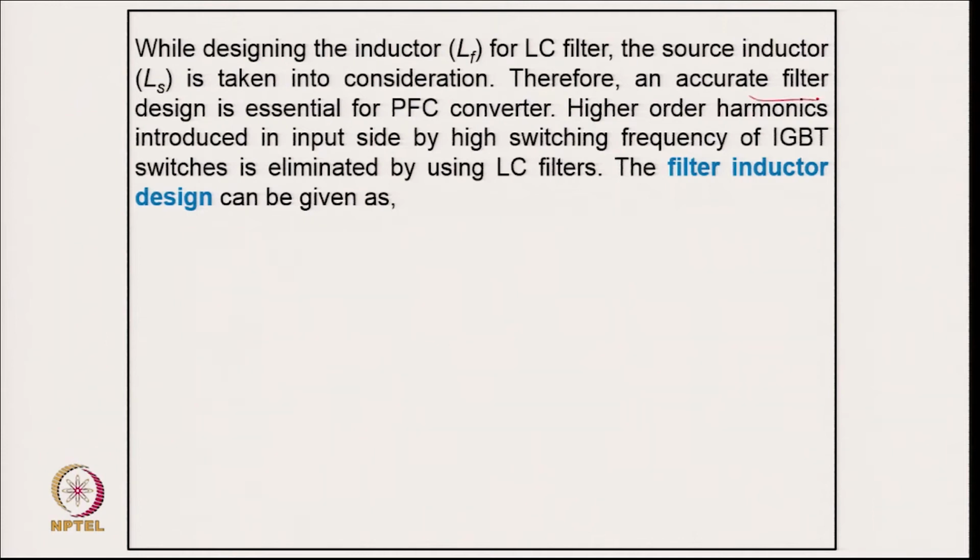Therefore, an accurate filter design is essential for a power factor correction converter, and the higher order harmonics induced in the input side by the switching frequency of the solid state switch are eliminated by using this LC filter.